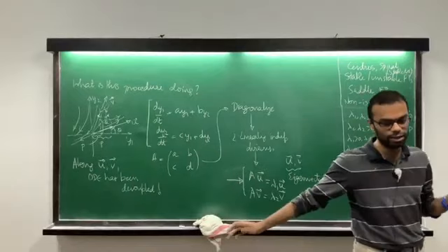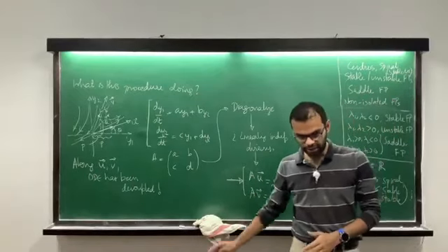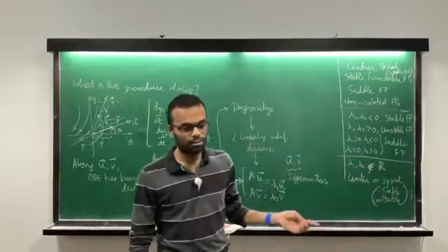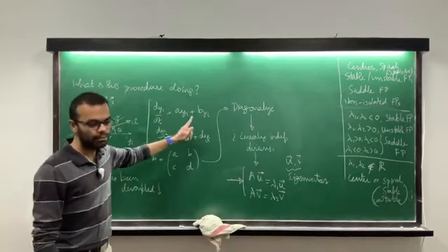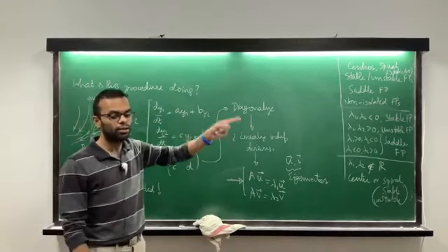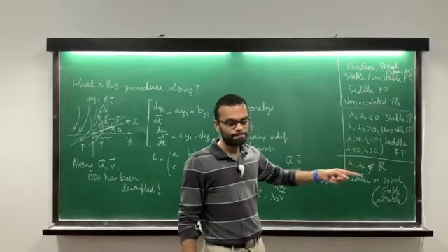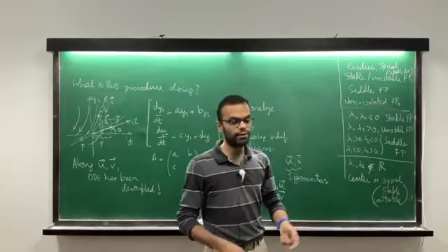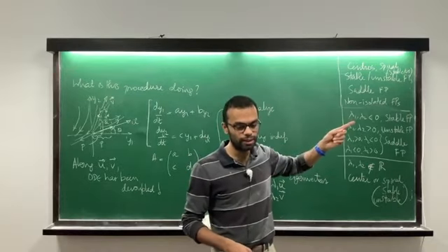So, then we can take any nonlinear system and do a linearization procedure. Again, I haven't told you how to do that, I will say that in the next session. But if you do a linearization procedure, you will basically end up with the same system, but now A, B, C, D depend on where you are, which fixed point you are close to, and so on. And so, you can have different fixed points having different stability just by following this procedure at each fixed point.